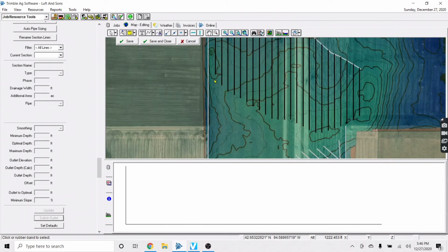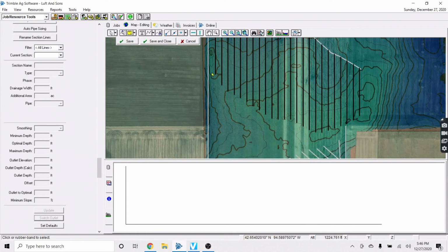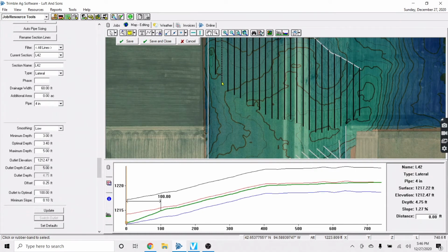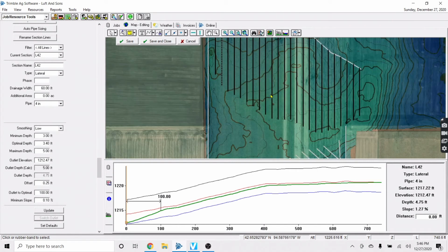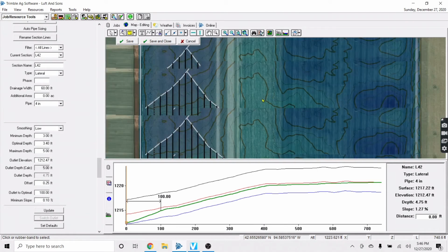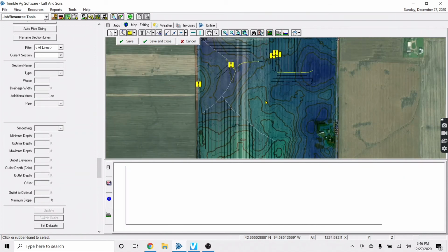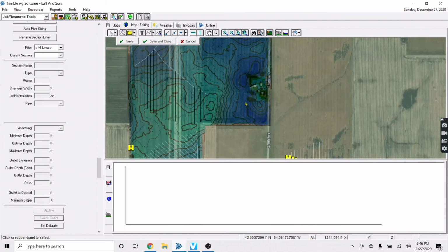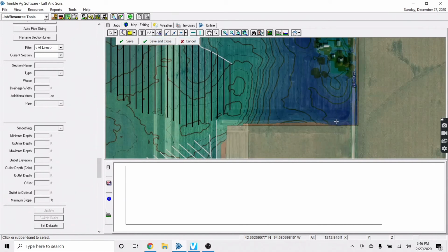It takes care of that side. Now we've got a little hole right here that either needs to go out right here if there's an outlet, or if not, it falls off 1, 2, 3. It falls off 3 foot. So if we had to get in there at 4 foot, you'd be 7 foot deep to get in here. Or if you sneak through here, you go 1, 2, 2.5. Somewhere between 6 to 7 foot deep to get back here to get into this low to take care of that. Skip that for now.